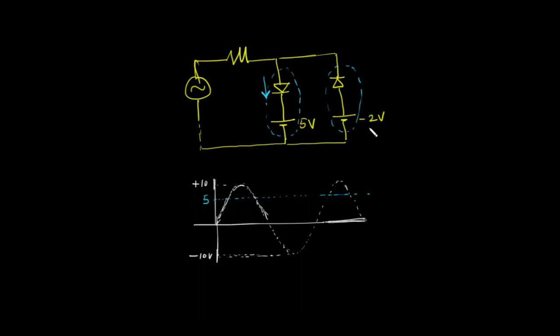And what is the second part of the circuit saying? The second part of the circuit is saying that, see, the diode is pointing upwards, all voltages above -2 volt will pass. So I can also mark the -2 volt level. Suppose this is my -2 volt level, here -2. So all voltages below 5 volt and above -2 volt will pass.